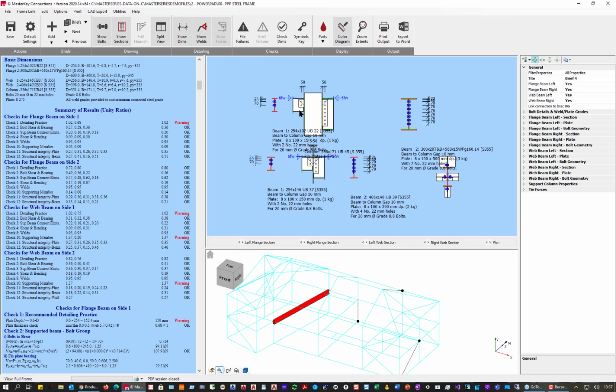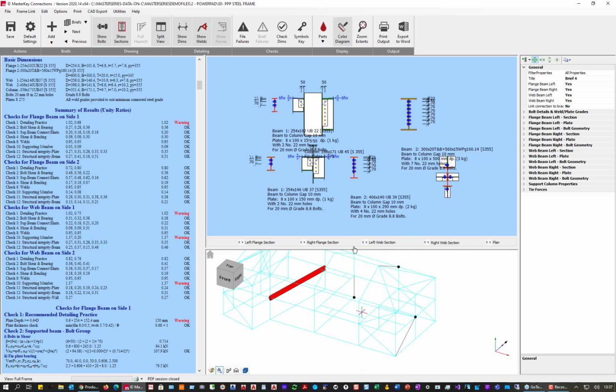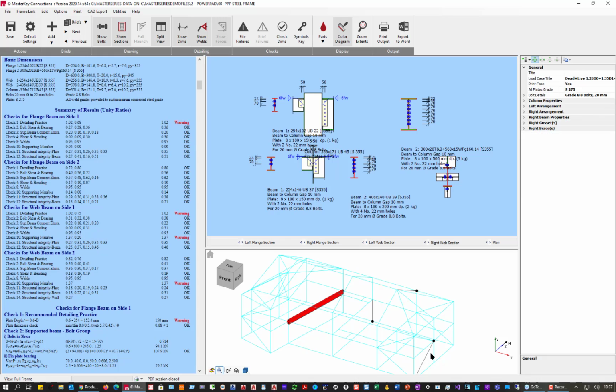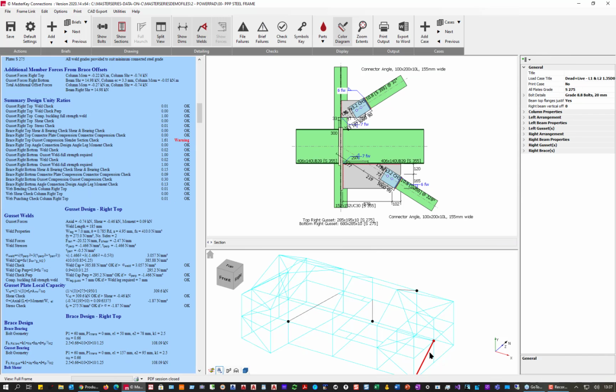We can make it bigger with set bigger, wider bolts, but we'll not worry about that at the moment. This is, I believe, a bracing member. Yep, we've done the full bracing connection and extended the end plate, and we're just doing several different connection types, all in that process.